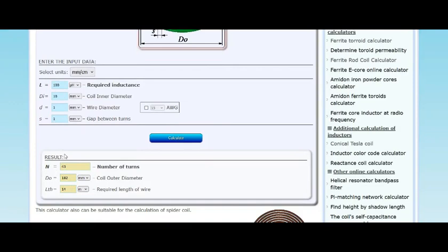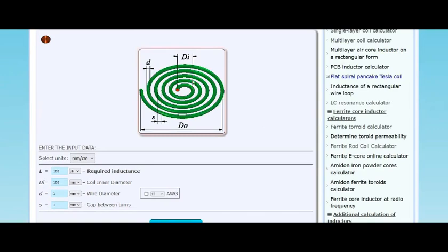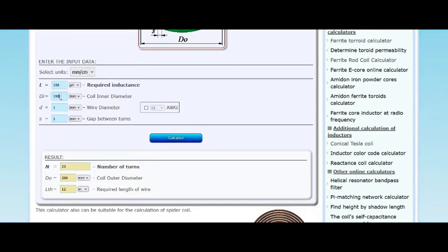So here, let's keep everything else the same. We see that it's 14 meters. So if we also wanted 100 µH, what if we made the inner air core 10 times as big? What's going to happen? Ooh, look at that. That's better, because now you only need 12 meters instead of 14 meters of wire to get the same inductance, and you get a double bonus that you don't have to sit there winding all those, because a lot of it's your air core now. Now, take that to the extreme. Let's go with 1,000. Now you need 20.